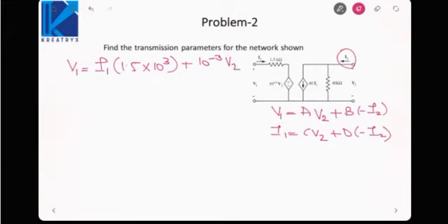Now what to do is, you need to substitute the value of V1 in terms of VOC. Or let us form another equation by KVL here. 100 is equal to I1 plus V1. We have three equations, we have three variables I1, V1 and VOC. So what we can do first of all is substitute VOC in terms of V1.